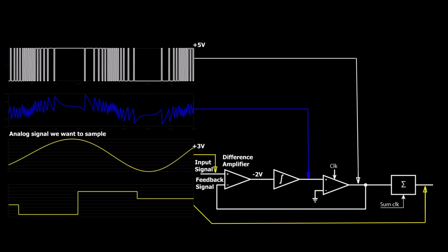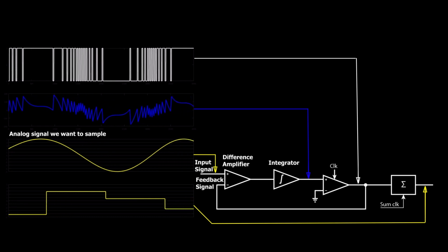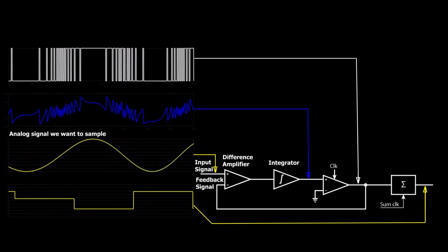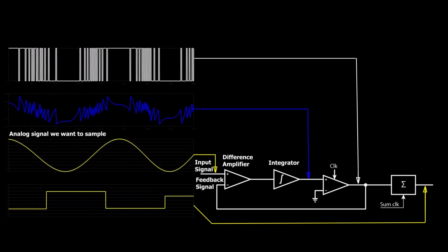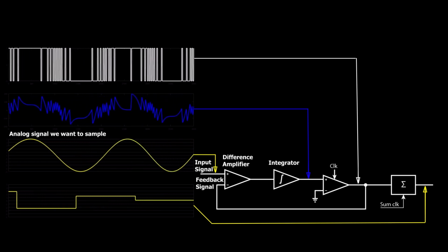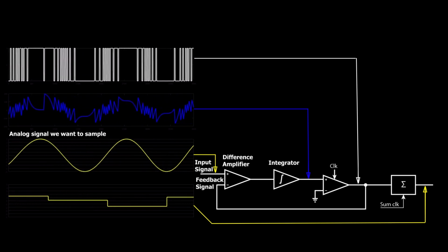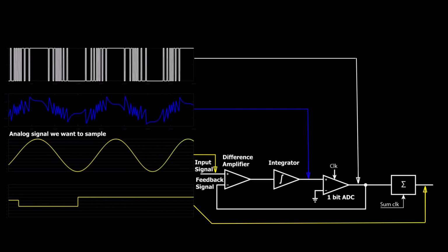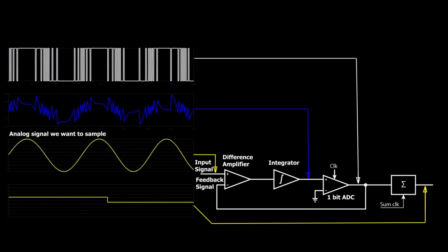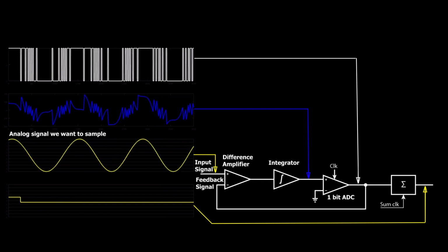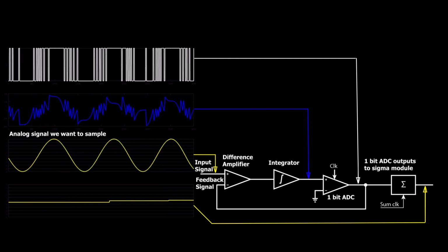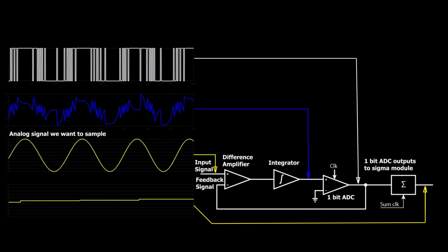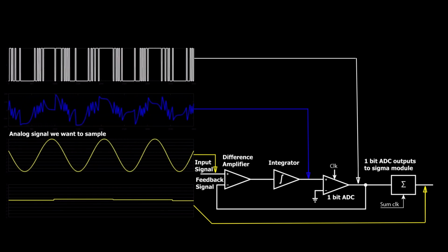And we now want to run the signal through a low pass filter. And the simplest filter is just a single integrator. But in practice, you might have several integrators in series to kind of tailor the aliasing characteristics of this ADC. And the whole point here is that the integrator time constant will provide a delay that is related to the feedback error. Cool. Now this 1-bit ADC that we developed will close the loop in the delta sigma converter. And this ADC signal is also the output signal, but let's just first kind of admire this feedback loop working, because it's just so satisfying, isn't it?